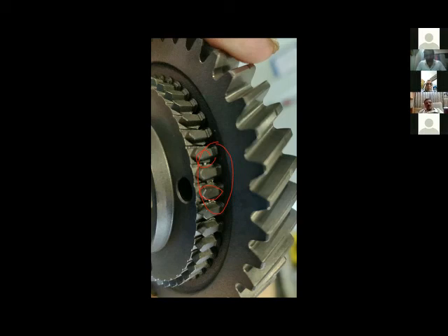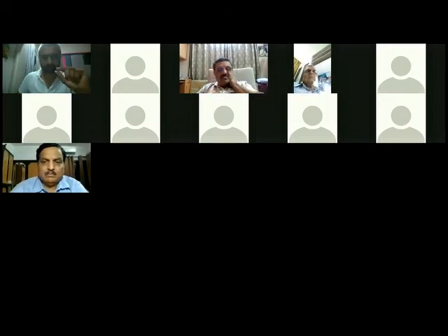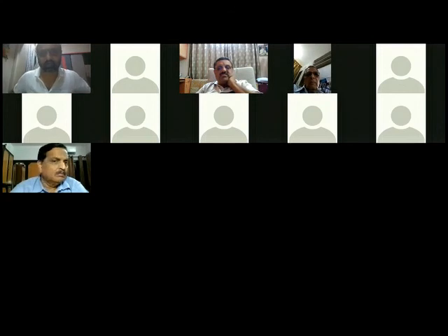So, could you answer this? Yes, like I said, the diameter is on the higher side compared to the clearance between the profile. So you need to reduce the diameter, or if shot peening is not required there, you can mask that area also.